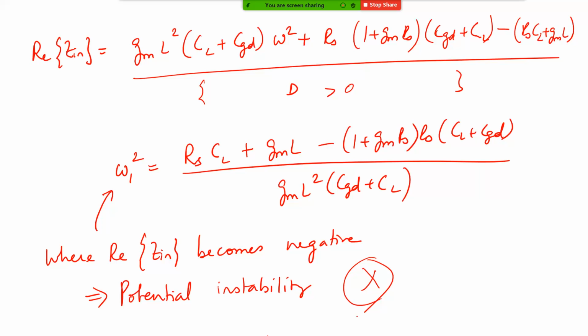Instead of amplifying the input signal, if the LNA itself is singing its own song, meaning the LNA itself is oscillating at some frequency, and you demodulate it, you will get one single tone signal which might be in the audio range or may not even be in the audio range. So there is absolutely no communication there. The LNA loses its purpose, which is a very, very bad thing. You don't want it to happen.